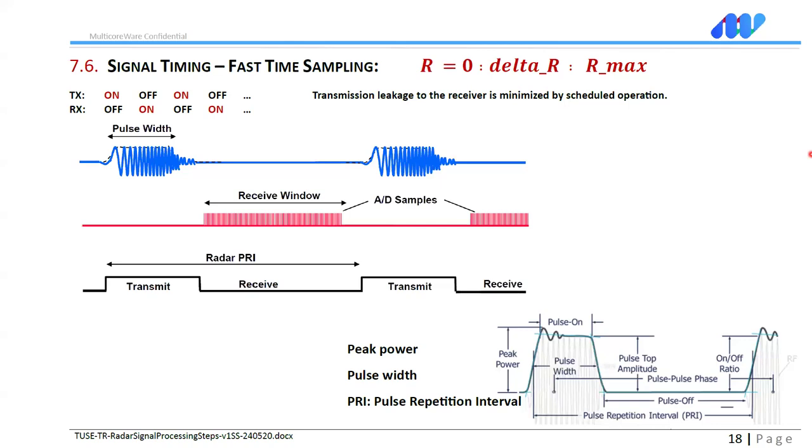For example, for mobility and transportation applications, say we have a range of 200 meters, this ratio could be larger than 100 decibels. And 100 decibels means 100,000. So you send 100,000 units of power, and then the received signal is just one. Almost nothing coming back. So it's very, very weak.